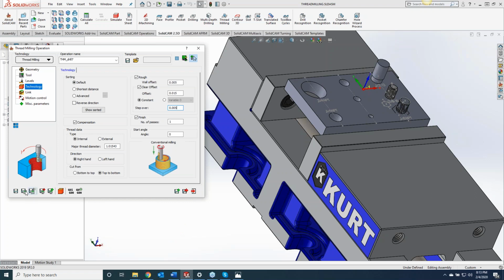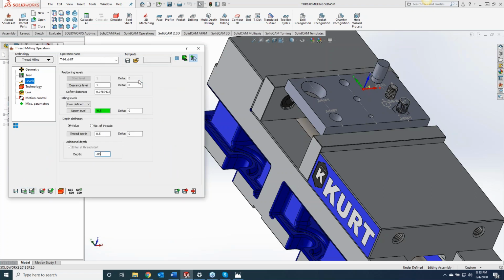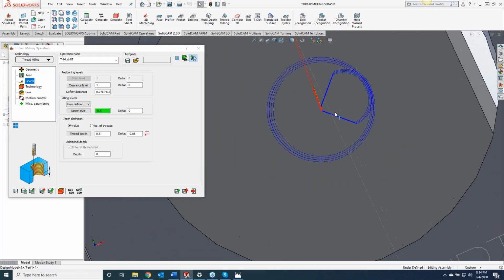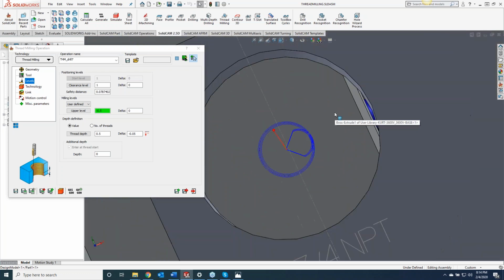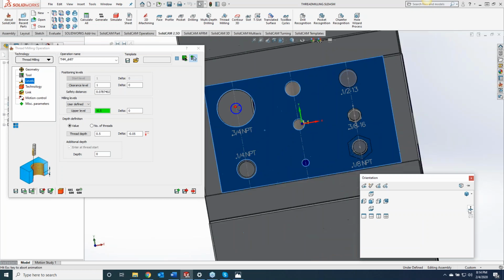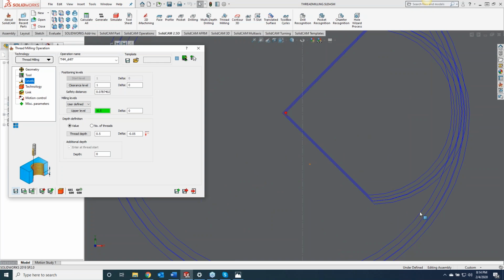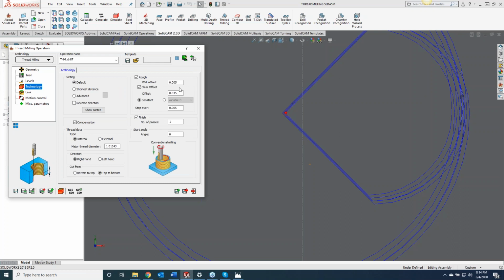And that's going to act as a clear offset, like what you showed in the profile passes as well, for roughing something and then using a finish pass to get it to its nominal size. So if we come in here, I'm going to zoom in to this specific tool path and get a straight down view, and turn off our tool here. So here is our clear offset of 15 thou. It's taking a pass, moving over 5 thou, taking a pass, moving over 5 thou, taking a pass, and then that leaves us with that last 5 thou, and that last 5 thou is taking the pass in there.